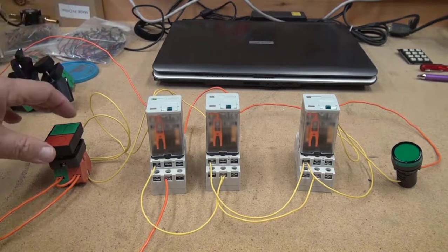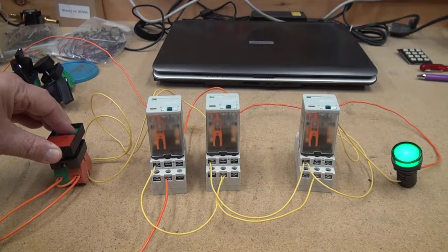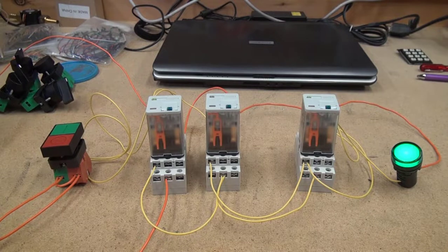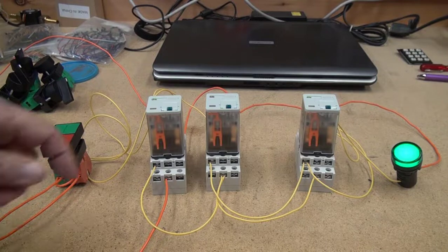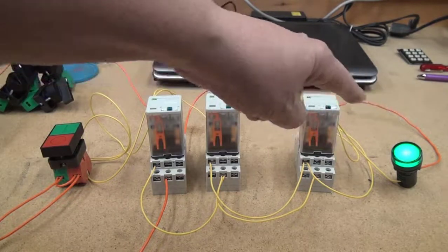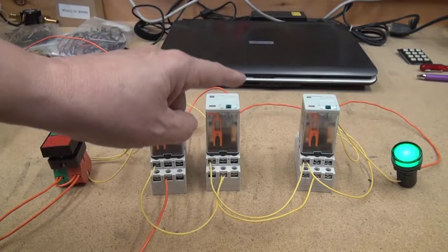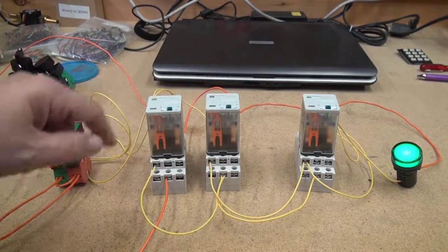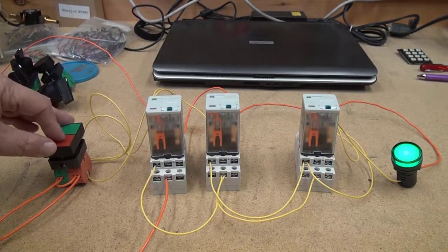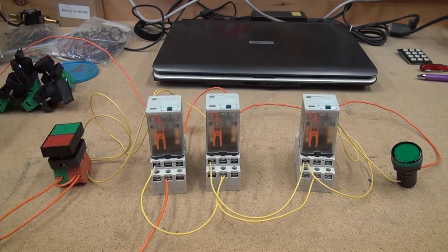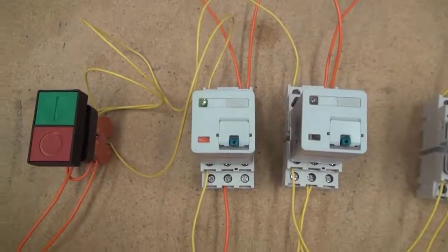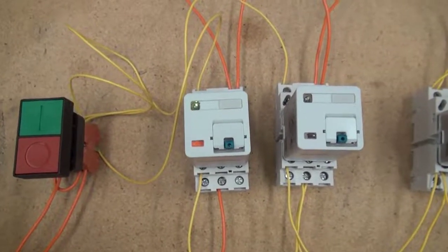So when I press the start push button, you'll see that the output turns on. I can release it. I don't know if you heard the start relay de-energize, but it de-energized. This output is still on because the contacts from this relay are sealing in the contacts that were closed, and these are closed, so that when I press the stop push button, everything turns off. So I'm going to see whether we can see the action here.